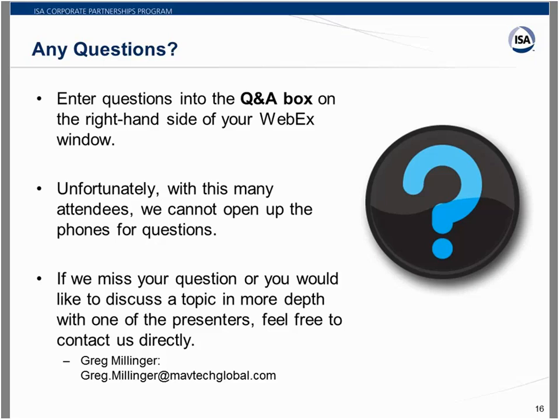Okay, next question. If we have multiple DCS systems from different OEMs, how can they be integrated for analysis into the same software module? What ends up happening here is that you can connect to multiple OPC servers, or if there's a native driver available for the system, you can connect to those.